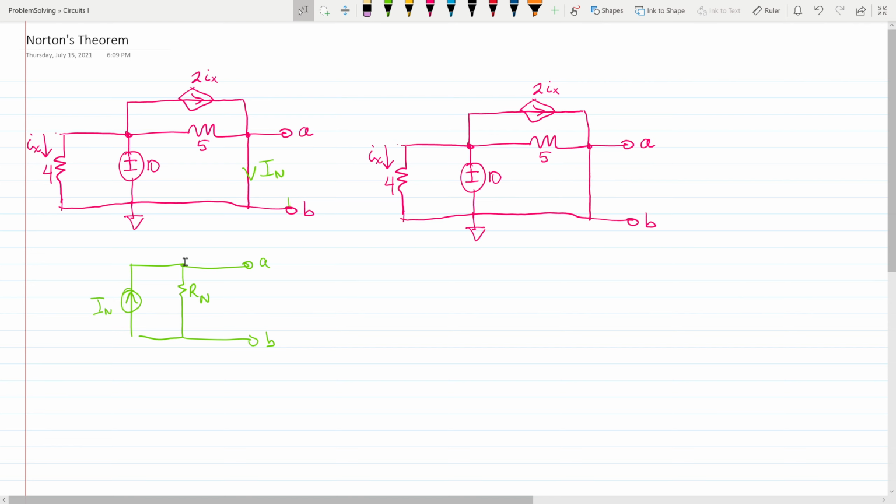So we know when we want to find the equivalent resistance of a circuit, we'll have to turn off any independent sources. In this circuit here, there is only one independent source, and it's this voltage source here. So you're going to switch this from 10 volts to 0 volts, because that's what turning it off means. And so if this is a 0 volt source, that's the same thing as just a straight wire shorting where that voltage source used to be. And that's correct from a circuitry level, because a wire means that there's no voltage drop across it.